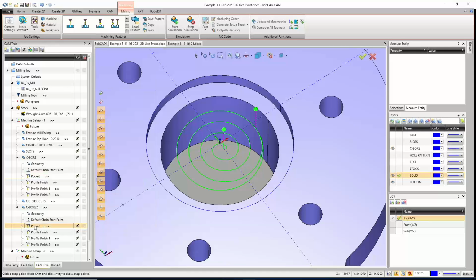And that's because this second pocket that we're doing, why is this showing the whole time? Blank you out. The second pocket we're doing isn't cutting the inside. It's just going in and cutting that area. It detected the open pocket. It knows that that's an open edge without us having to go and extract the edges off the pocket or draw them out and then convert that wireframe piece of geometry.